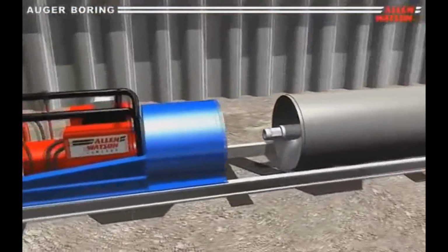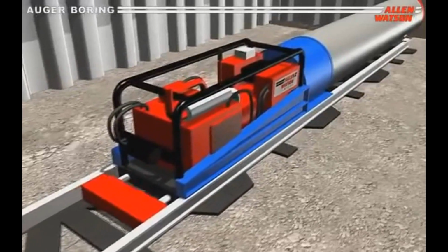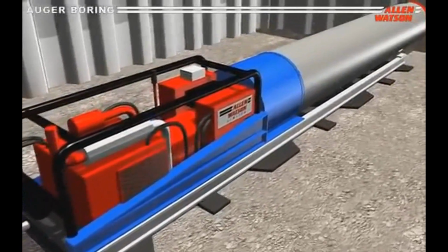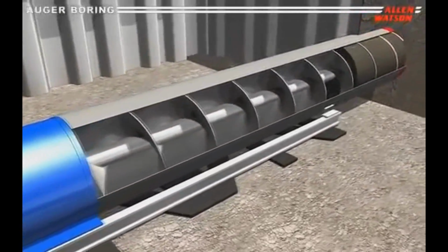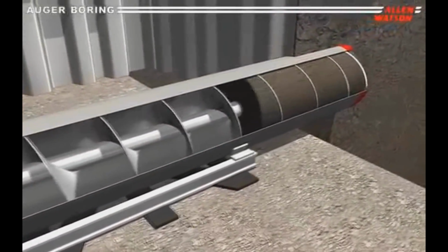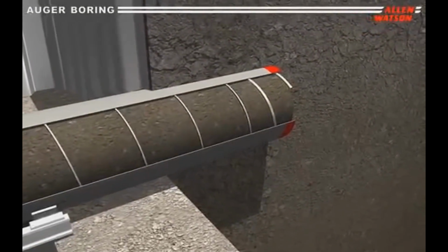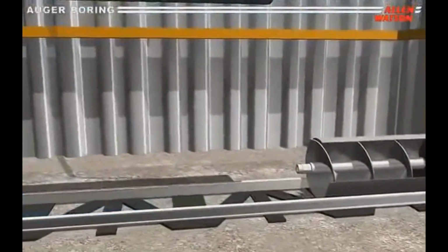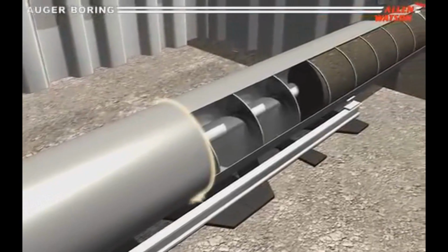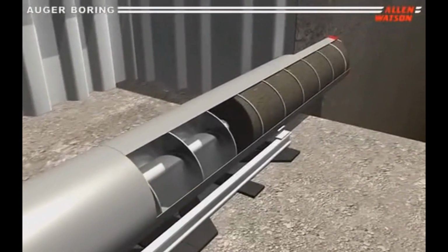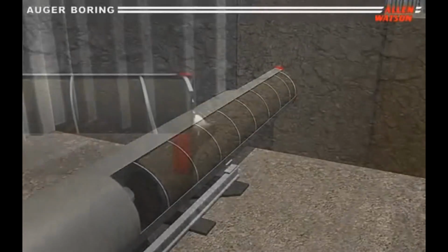Number of borings. For buildings, a minimum of 3 borings where the surface is level and the 2 borings indicate the regular stratification may be adequate. 5 borings are generally preferable at building corners and centers, especially if the site is not level. On the other hand, 1 boring may be sufficient for an antenna or industrial process tower based in a fixed location with a hole made at the point. 4 to 5 borings are sufficient if the site soil is non-uniform.